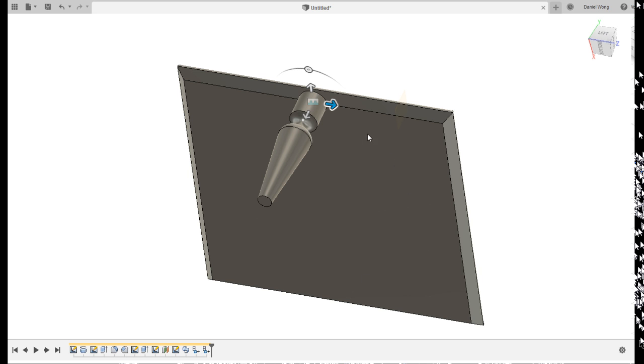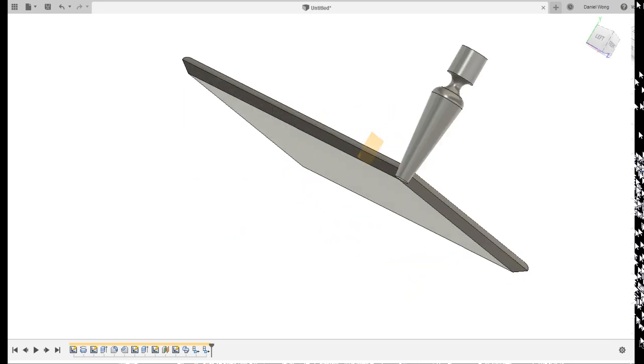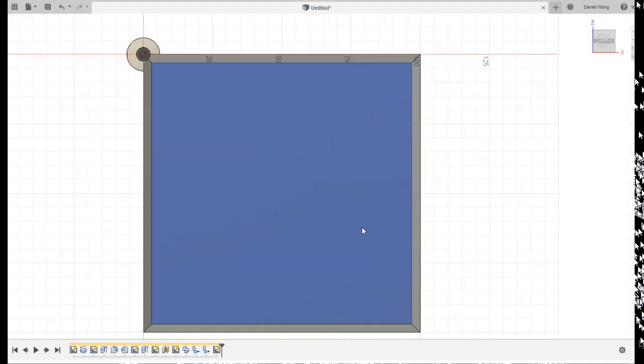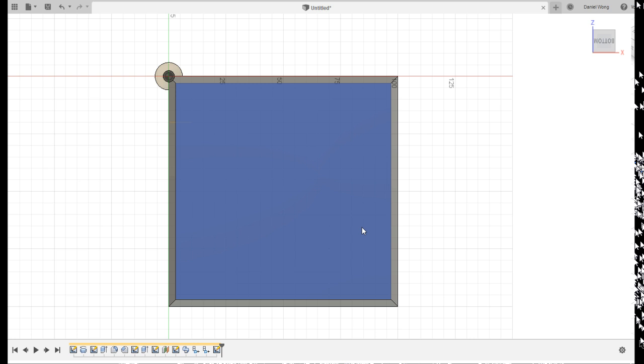Okay, so you can see that this is obviously not going to work. So let's cancel that. And let's create a sketch on this bottom face here. What we're doing is defining a rectangle or square that has the corners equal to points that I want to join my legs to. Does that make sense, everybody? So what I'll do is inside the sketch, I'll just offset these by a distance of -5, which is the radius of those cylinders that we originally made. And that should sink it far enough, like so. Does everyone have that?